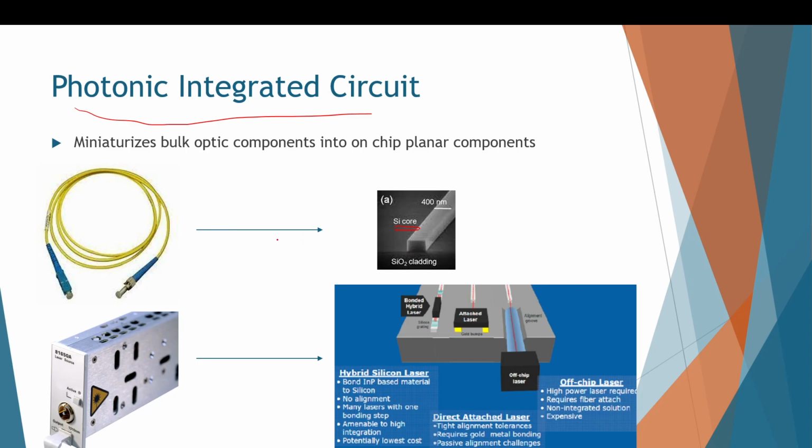In the case of on-chip waveguides, we need even higher confinement, because we are dealing with even smaller dimensions. You can see the scale here. Because of that, we choose silicon as the guiding material. It has a higher refractive index, which will depend on the wavelength, but is around this number.